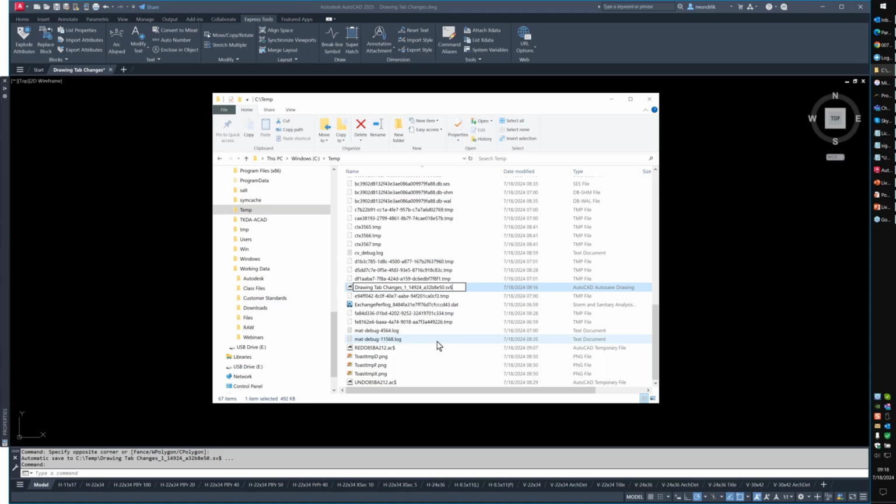All right, Corey, regarding the autosave temp DWG, I'm not sure if this is the right thing to do, but when this happens to me, I found that I'm unable to save normally unless I close the program. I did find another workaround where in Task Manager, there's a subtab called AC Core Console, that if I force quit that, I continue normally. I haven't seen AC Core Console running any other time, and I haven't noticed any issues from closing it.